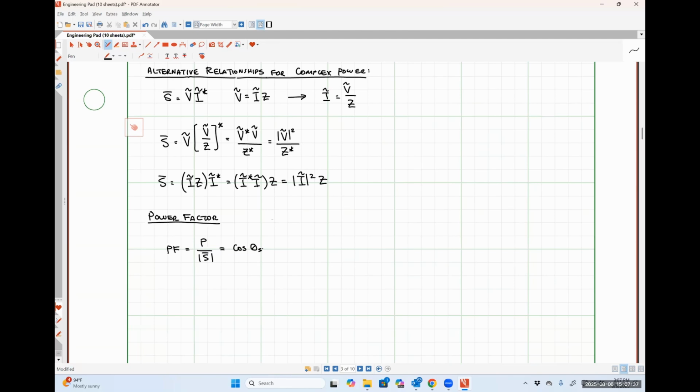And by pay to generate, I mean specifically things like the cost of coal or natural gas, but also the cost of the infrastructure that is needed to deliver power from the generation station to the end consumer and stuff like that, right? So average power is what we pay for as consumers. Apparent power is what the utility pays for to produce, okay?